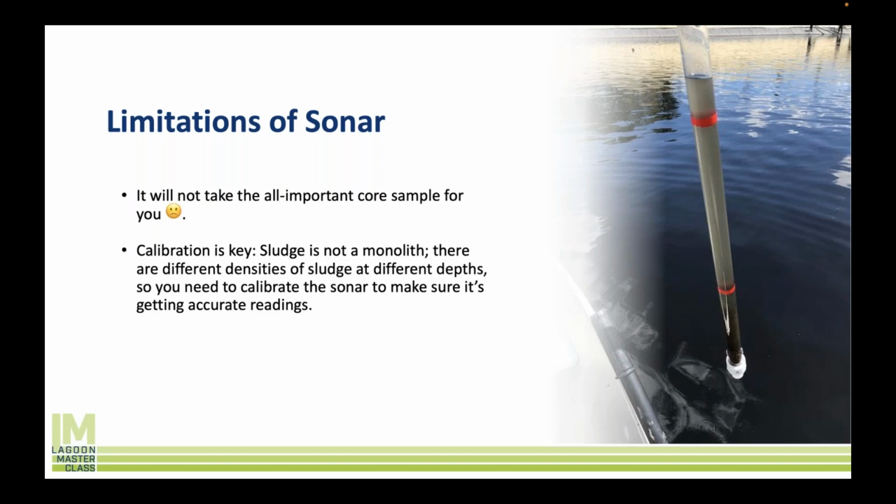And so I think calibration is really key with this. Especially if you're going into an industrial lagoon where you've got different types of solids. If you don't calibrate it correctly, you don't validate the data correctly, you could be getting data from this that's just simply not right.